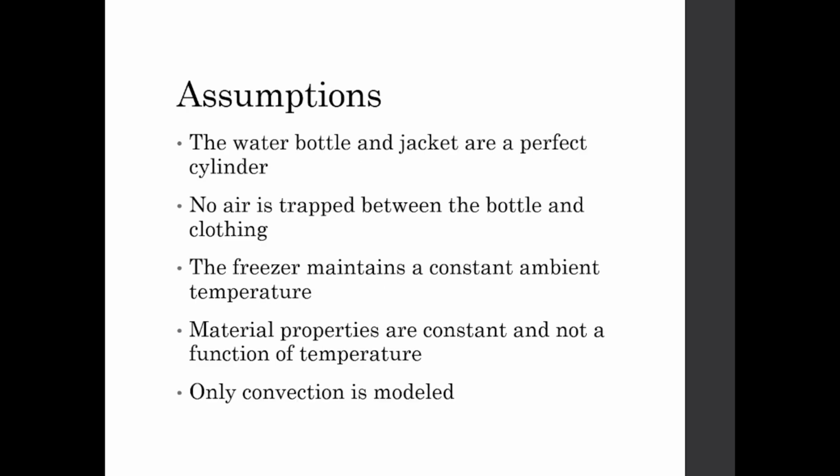The assumptions that this project is making are that the water bottle and jacket are a perfect cylinder, which is not exactly true, but it is close enough for the sake of modeling, that no air is trapped between the bottle and clothing, that the freezer maintains a constant ambient temperature of negative 19 degrees C, that the material properties of water are constant and are not a function of temperature, and that only convection is modeled.